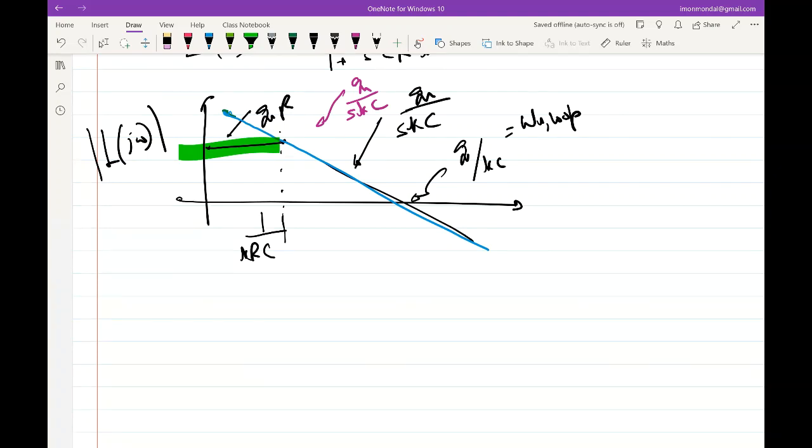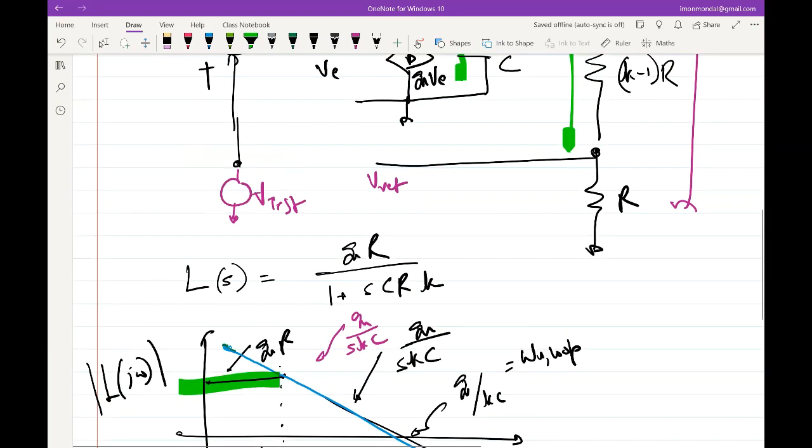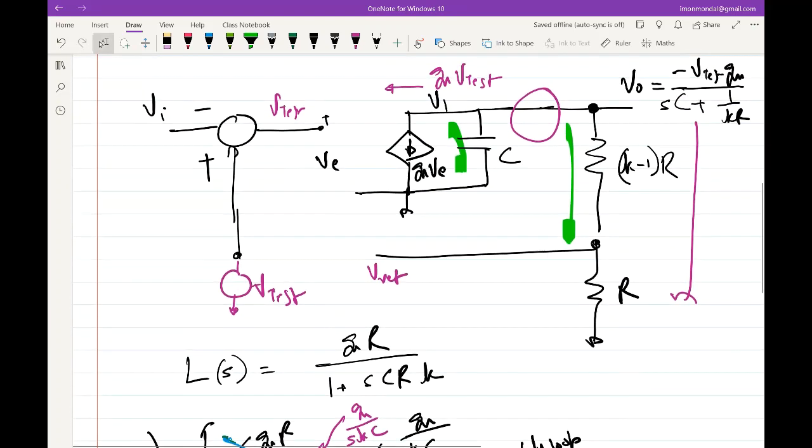Any questions? Sir, this can be used as a voltage control voltage source after this. Yeah, exactly, right. So his point is, then it seems like this configuration can be used as a voltage control voltage source after I hit the pole, because there seems to be no difference between what was happening if I had an ideal voltage control voltage source and what is happening now.